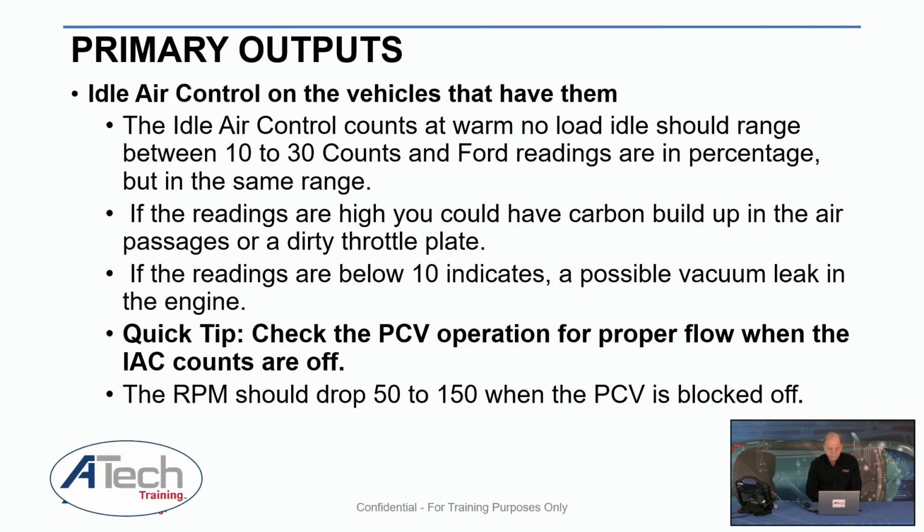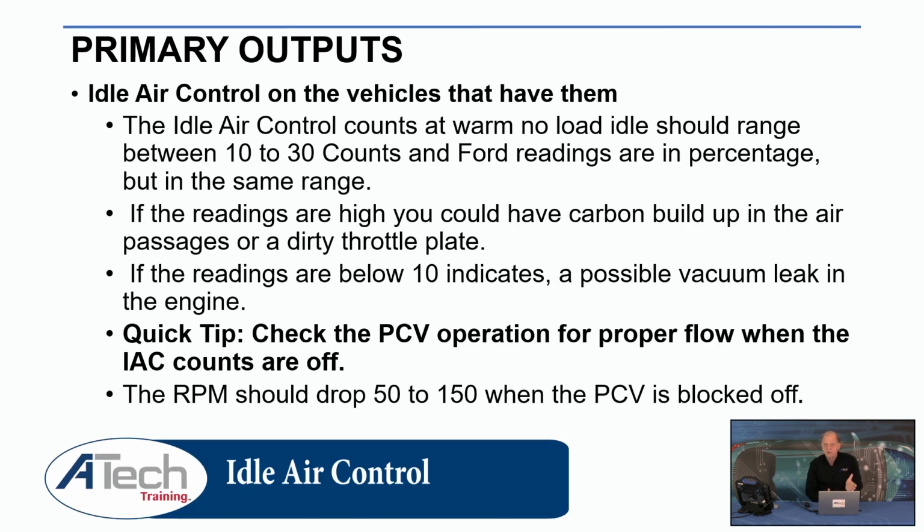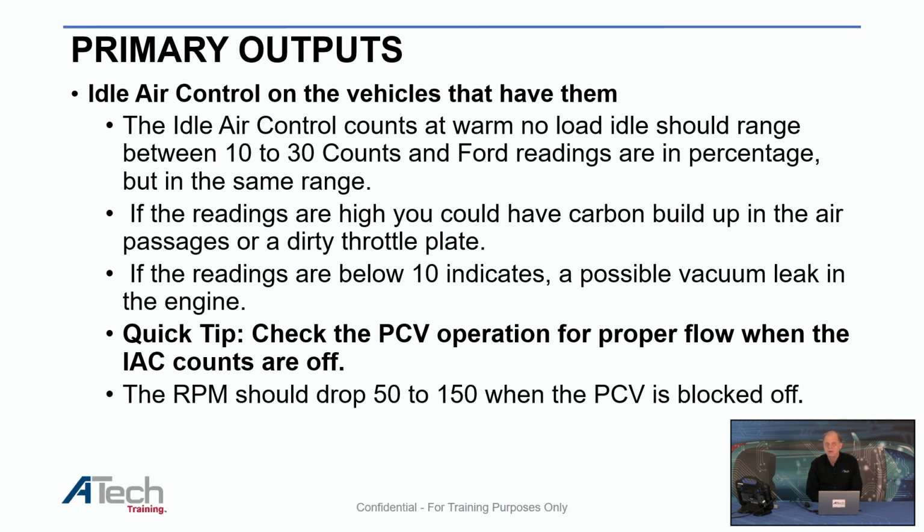Now, idle air count, I've already talked about this. Idle air count should be between 10 and 30 on the older ones. Fords are going to be in percentage, they're not going to be in counts. Chrysler and General Motors are going to be in counts. If it's high, look for carbon or something wrong mechanically on the engine. If it's low, look for a possible vacuum leak. Again, check the PCV valve.